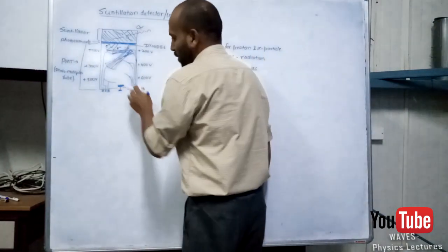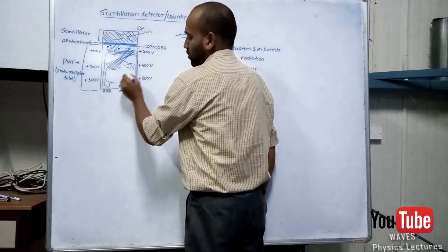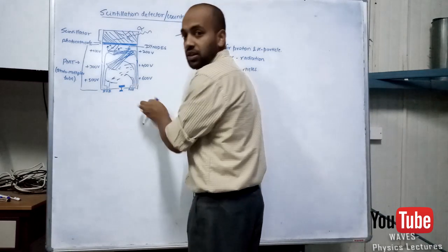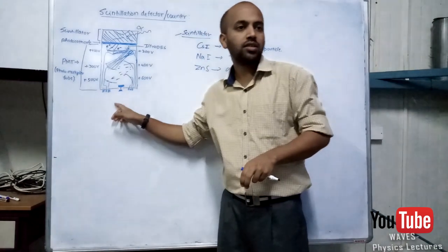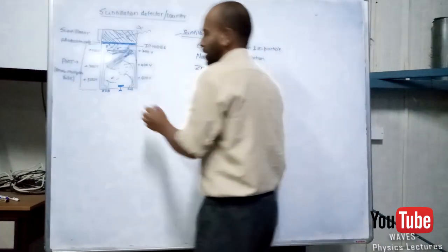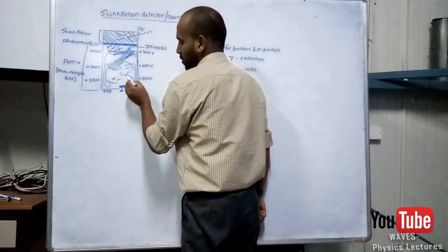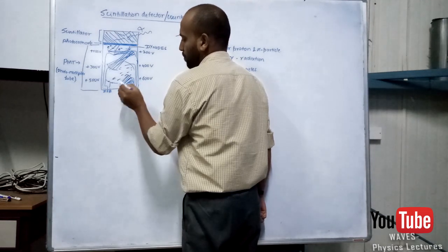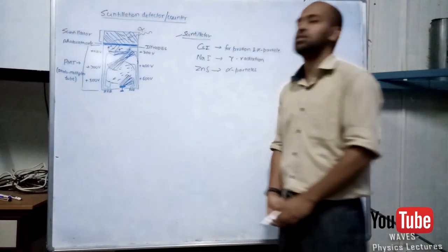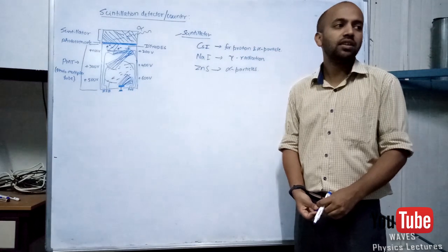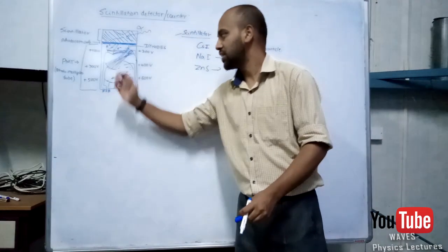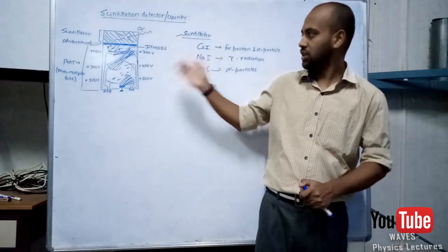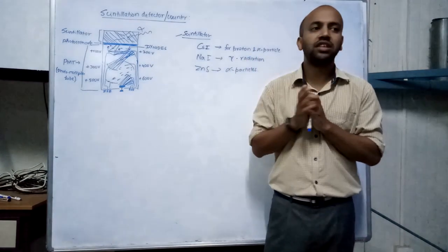So finally, when you are going to get the signals from this end and this end and so on, the signal is accepted by the anode, and this will be nothing but a number of signals. As a result, the signal gets multiplied. Is it clear? And then we can read that signal, and this is the output in the digital part. We have the amplifier and the electronics to check the output. So this is exactly how a scintillation detector works.